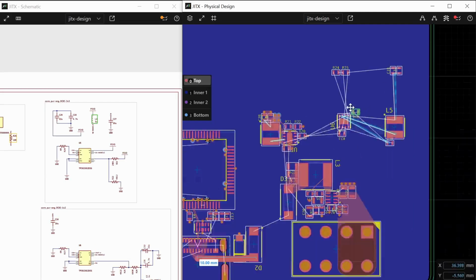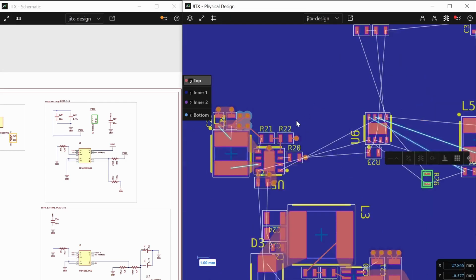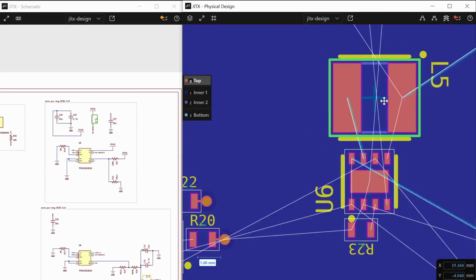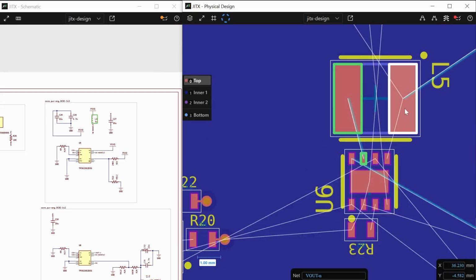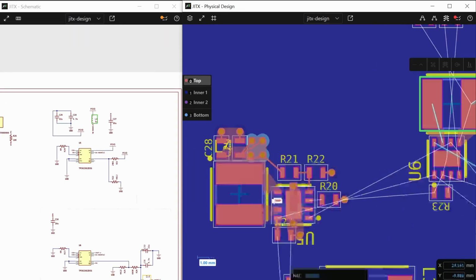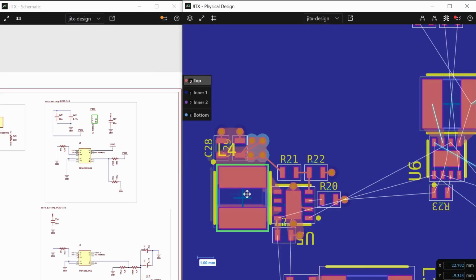We have some layout reuse to demonstrate, but for showing the power regulator layout, let me just re-demonstrate everything. So, inductor into place. Press C to create regions. Move this there. Actually, I can move this a bit closer as well.